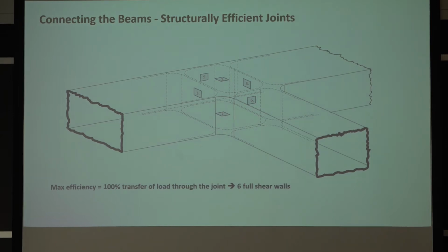Okay, so this is just like the bicycle lugs we were talking about. The bicycle lugs really provide a very similar effect to this. They provide that joint stiffness that you really need in order to have an efficient structure. I tried for about a month or so to figure out how you could fold up steel to make a structure like this. I never really succeeded. If you come up with one, let me know. But this is really where it's at. This is a really critical part to structural optimization, to make sure you have efficient joints.